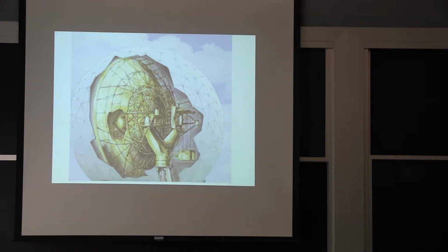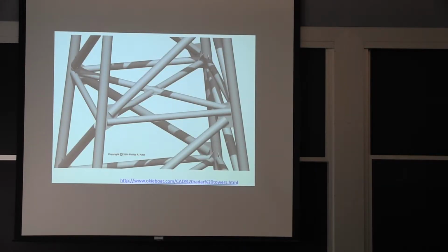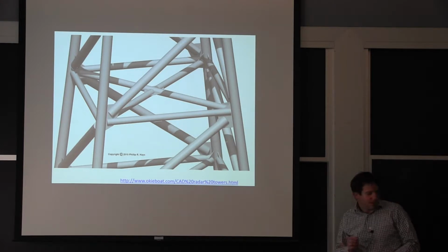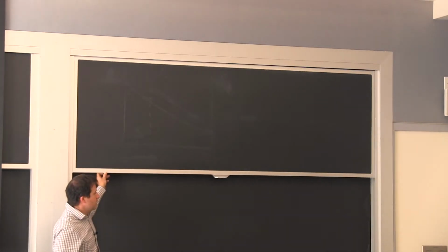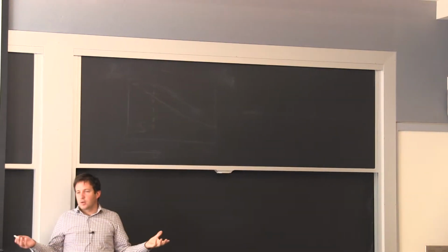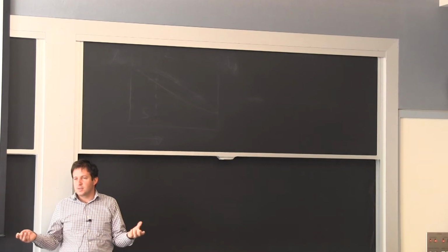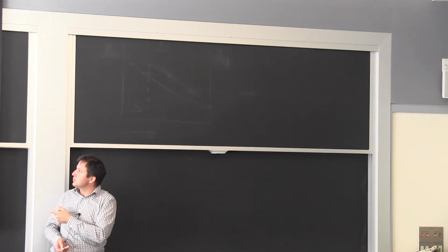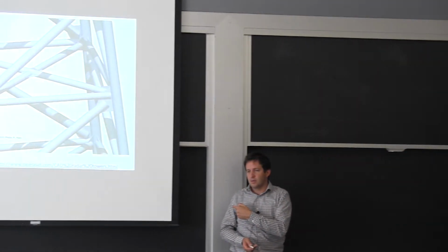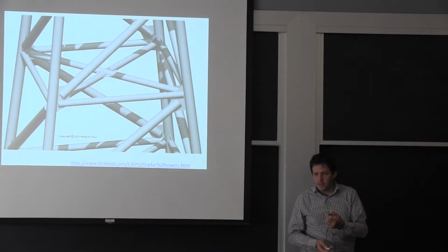Yes? So back on the welded structure that you had, where you break down the plates at the end, doesn't that also result in the plates being in tension that are welded to the main struts? It does. This is a good question. So why are we wondering about this? The two reasons: tubes are long, and therefore if you increase their thickness significantly, it's a big difference in weight. Relatively speaking, the plates can be thicker and not change the overall weight as much.